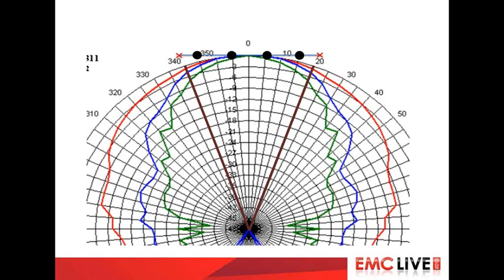Now, this actually holds quite a lot of information. If you look at it, you've got your greatest power density, your greatest volts per meter at the bore sight. And then with distance to right or left, you can see, let's use the blue line, that the illuminating power is dropping off as you go rightwards towards the rightmost red cross. So for instance, let's say at the extreme where the brown line crosses the blue line, we have, what would you say that's, 2 dB? We have 2 dB of loss. So although our bore sight might be at the intended volts per meter, in fact, at the right cross, and don't forget these crosses actually represent a circle that passes through calibration points, it will be 2 dB down.